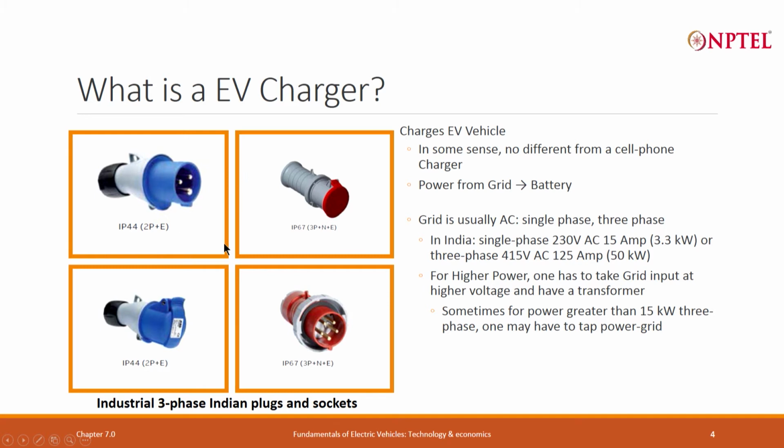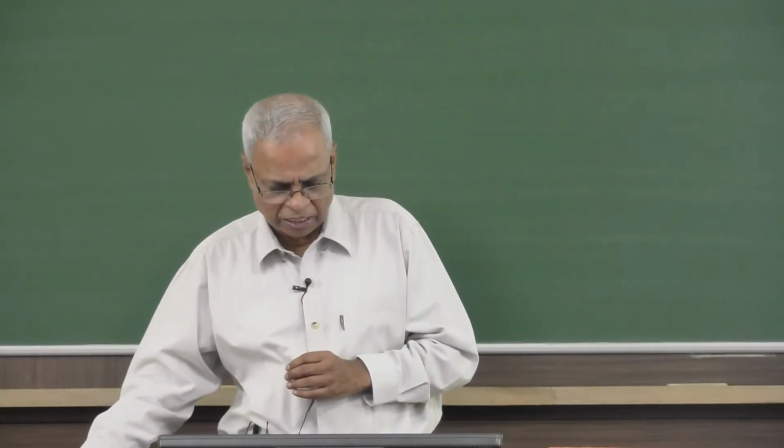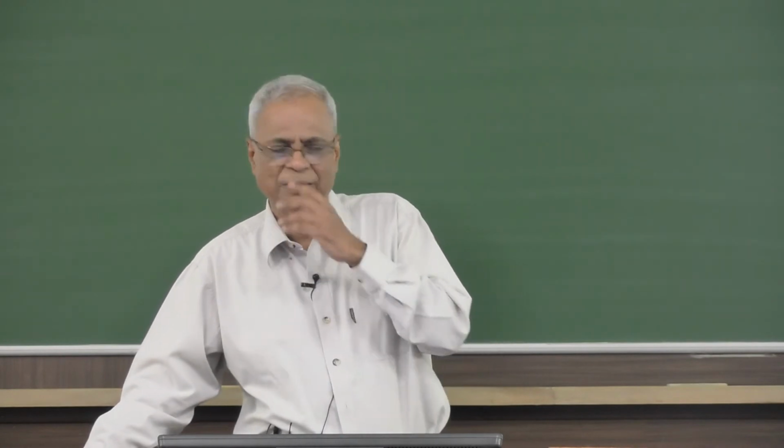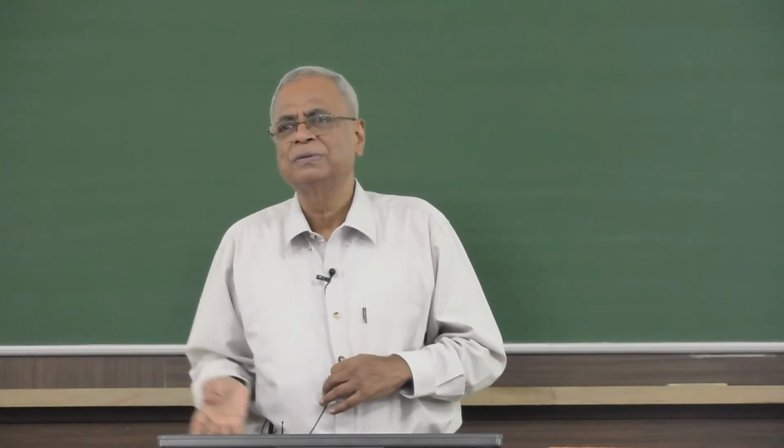Can you use the standard 15 ampere socket that is used at homes, single phase? Well, yes and no. The number of times that a socket can be connected, removed and connected again is limited. So, if you are going to have an EV and you are going to do it about 1000, 2000 times, that no longer remains reliable. So, you will generally prefer to use something like this. If you do use the home socket, you will have to be prepared to replace it.